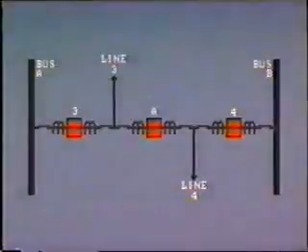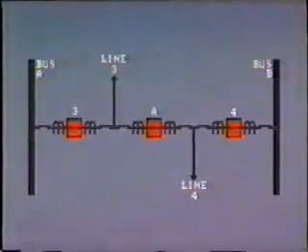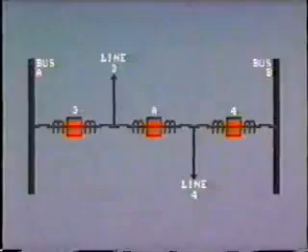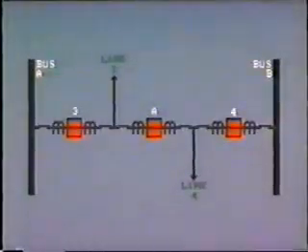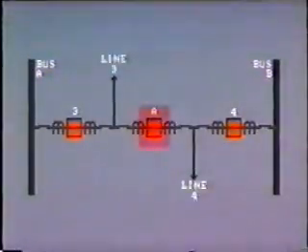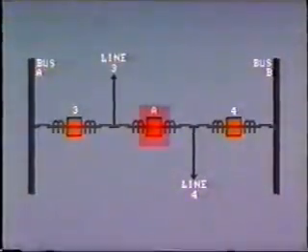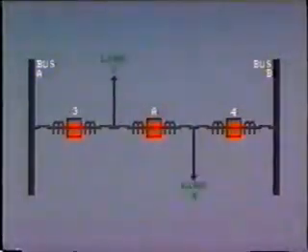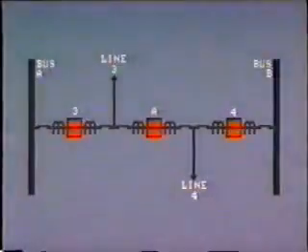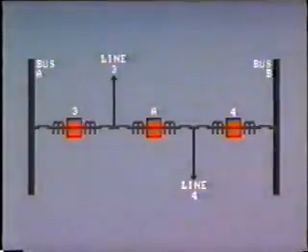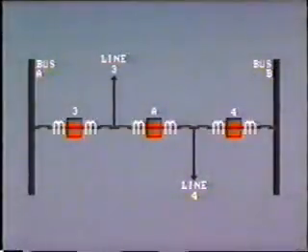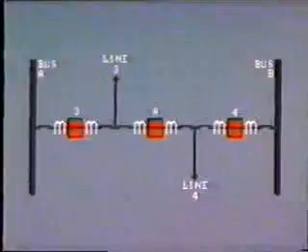A more economical version of this bus arrangement is the so-called breaker and a half. For simplicity, we show just 2 incoming circuits here. You can see that they share the middle breaker, hence the term breaker and a half. Normally, the shared breaker is closed, and both line 3 and line 4 are fed by the 2 buses operating in parallel. You will observe that CTs are installed on all breakers so that both differential and line protection can